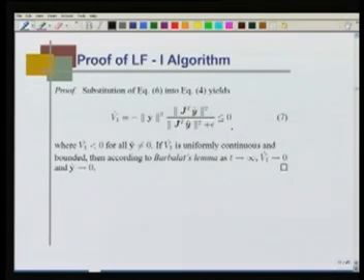And that assures us that if V 1 dot goes to 0, then this quantity also will go to 0, okay. If V 1 dot is uniformly continuous and bounded, then as t tends to infinity, V 1 dot tends to 0. If V 1 dot tends to 0, you can easily see that y tilde will go to 0.